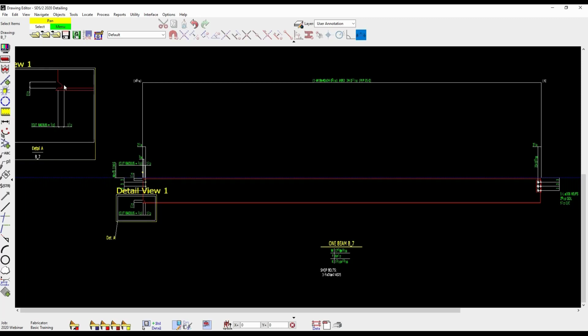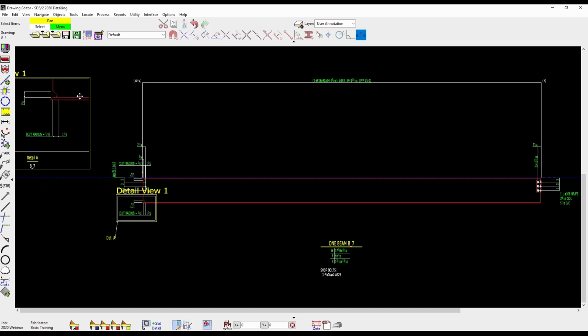It makes them both exactly the same, taking that information off. So auto update will redetail it using those detail settings. Synchronize will make that exact copy of this detail view, redetailing and recreating that detail view. So let's go ahead and keep this one here.